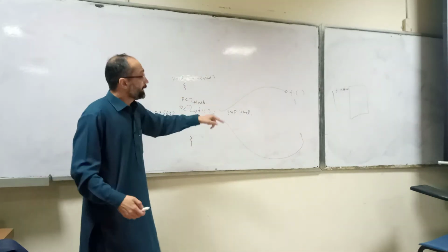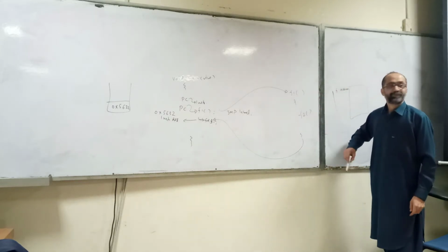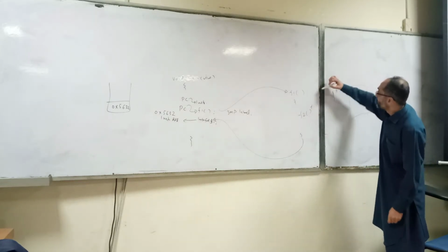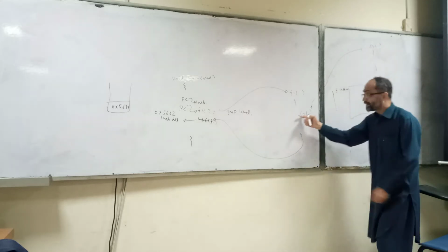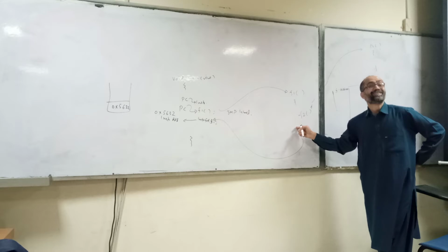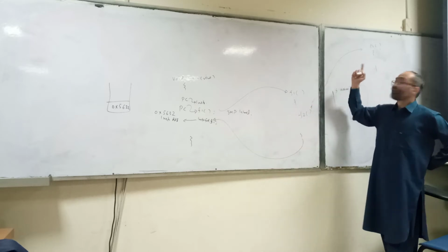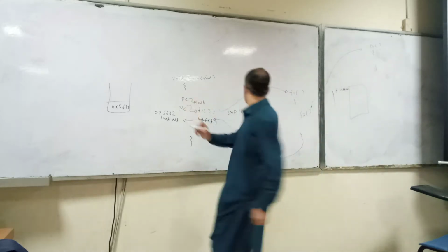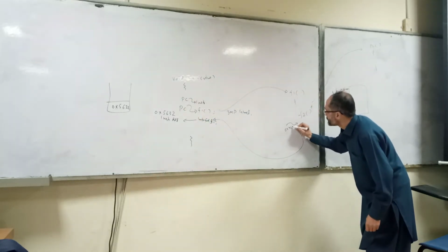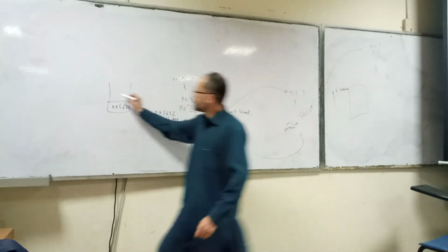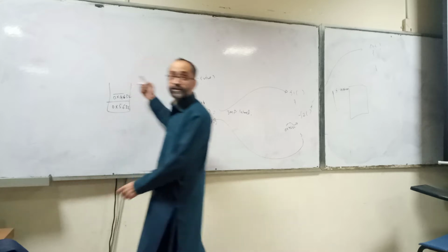If you are calling another function within this, let's assume f2, then you are jumping from this function to another function f2. In this case, the address of the instruction that follows f2 is pushed on the stack. Let's assume this instruction address is 0x9632. Then 0x9632 is pushed on the stack.